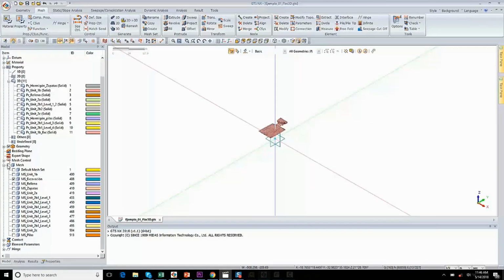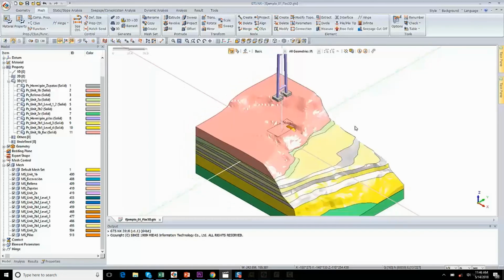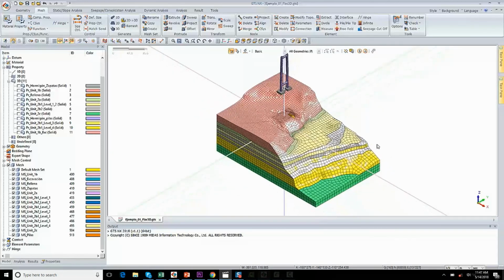And hence why we've now created material property ID 11 for the set to be excavated. So we see here now, everything else is ready, so we can save it. We've prepared the model by moving the sets, also by assigning an additional property. So now we can get ready to export.